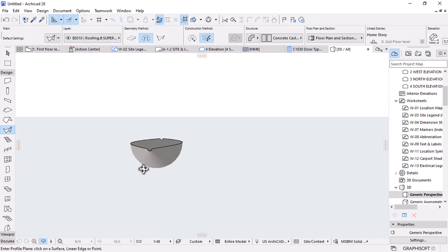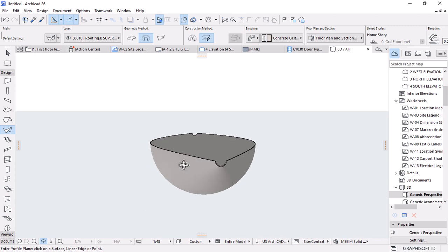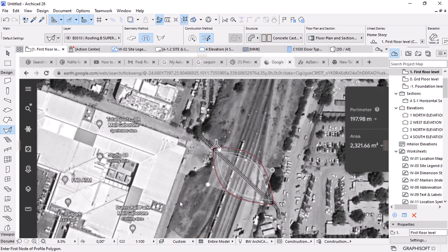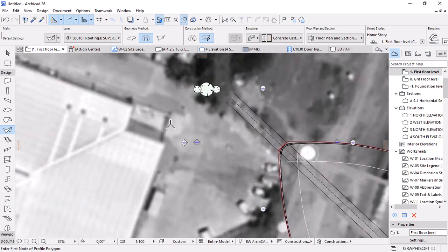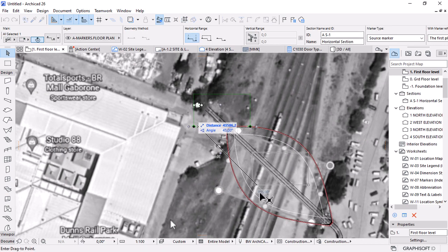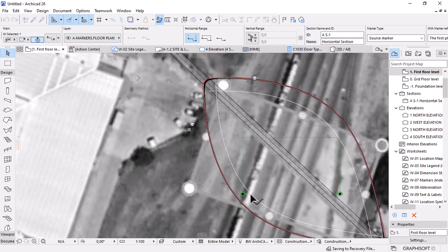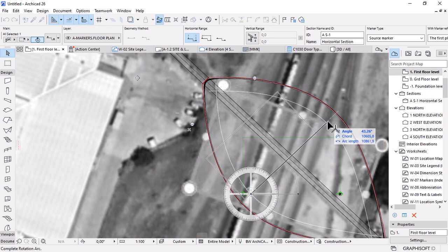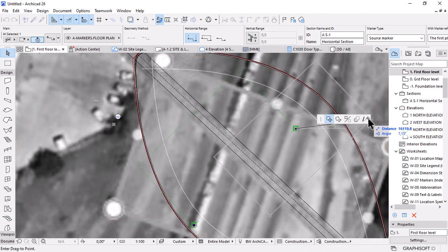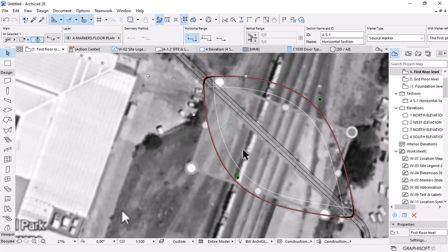It didn't happen, I don't know why. It's giving me a problem. This has to be inverse or the other way around, a mirrored copy of this. So let's do this. I can draw a section and try to rotate it on a section. So pick this section, put it here, and let me rotate it according to this axis. Make sure it's cutting the element on both sides.